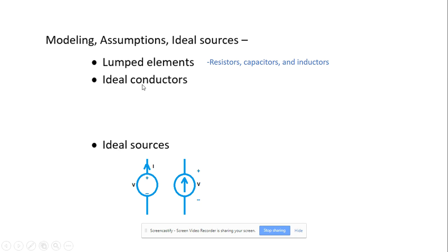But really, what I think I'm leading into here is that with ideal sources, what we will be discussing throughout the semester are ideal voltage sources and ideal current sources. Now, it can be sort of aggravating because there's no such thing as a current source in real life, right? You can't go to the store and buy a current source. But voltage source, you think of a battery, that is exactly what we're dealing with. We use current sources when we're looking at circuit analysis just to discuss, okay, there's a specific current here, and we can easily represent it with a current source.